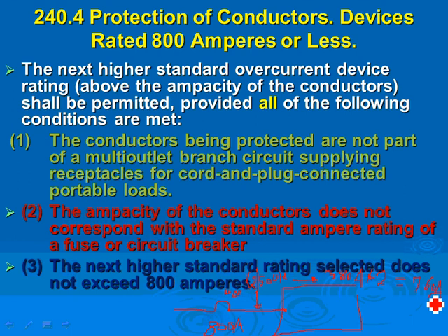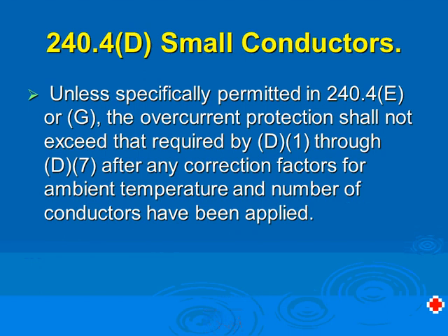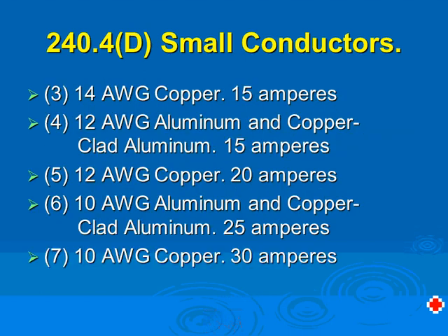The only exception, of course, is that it has to be the next standard size, and you can't use it for cord and plug connected portable equipment. So you're dealing with panels and so forth. So that's your conductor protection. Now the small conductor rules, guys.